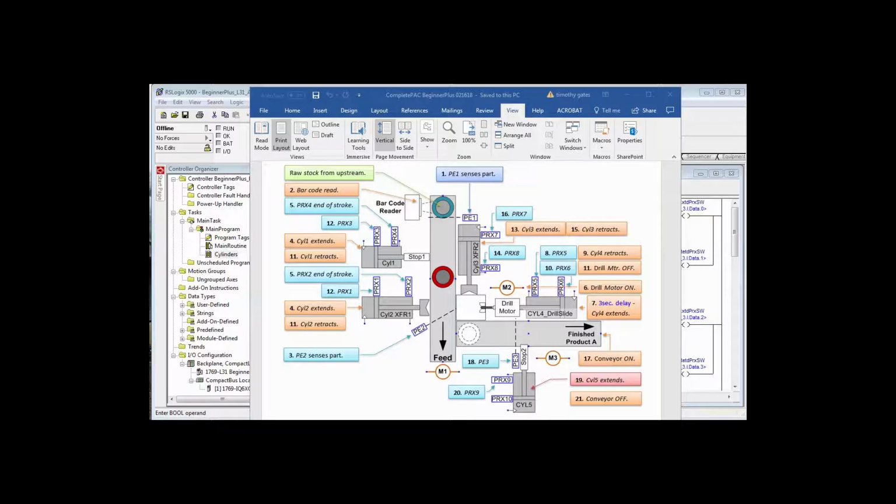Another reason for delaying the extend, going back to number 8, is if you have done a lot of hand drilling, you know that it takes a few moments for the drill bit to auger out the debris, like a screw conveyor, an auger. It takes a little while for it to clear the debris out of the hole, so you want to leave it running.